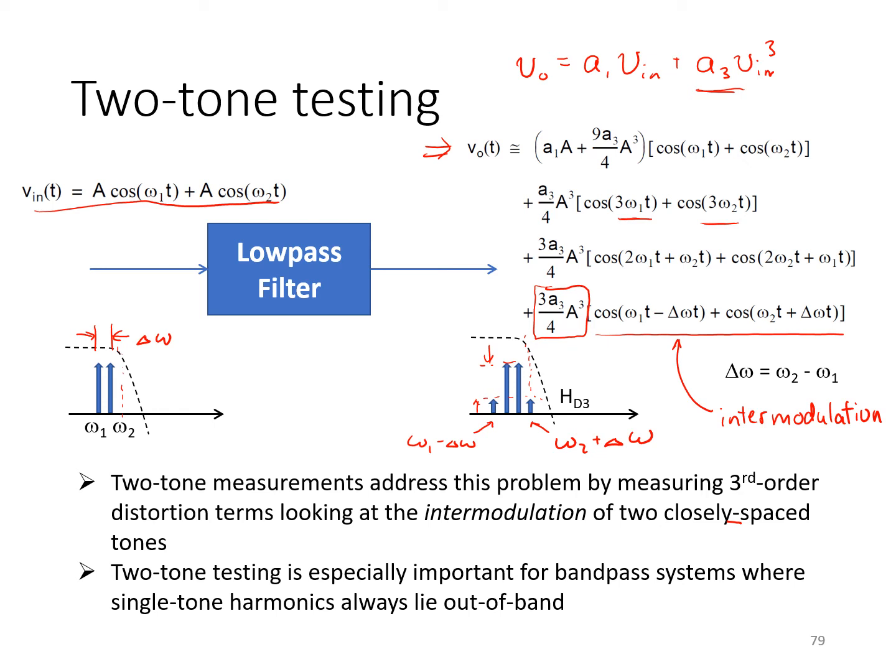This type of two-tone testing allows you to measure linearity by stimulating the circuit at very high frequencies at the upper limit of its bandwidth. This can be important because some types of nonlinearity are frequency dependent, and although we've derived this result assuming a memoryless model, the very same behavior is observed when we consider nonlinearities with memory.